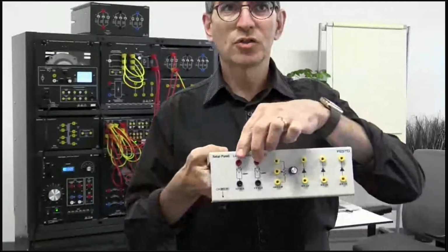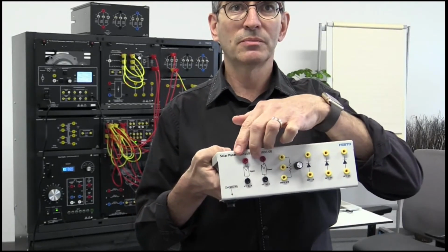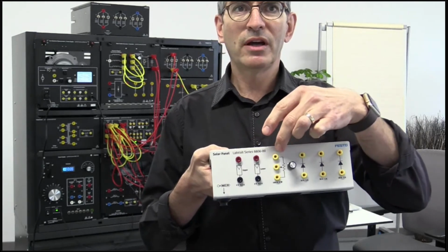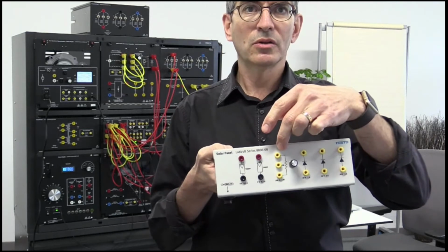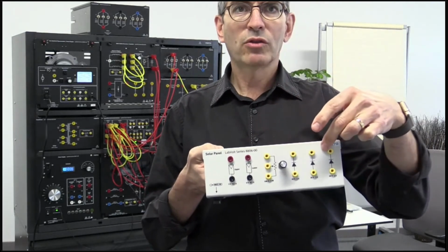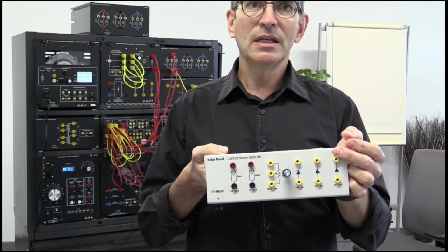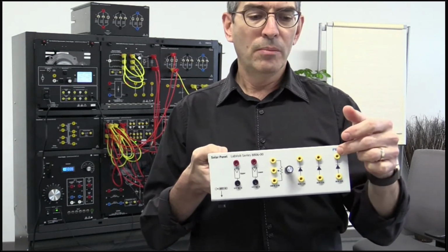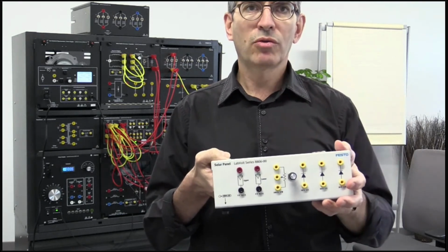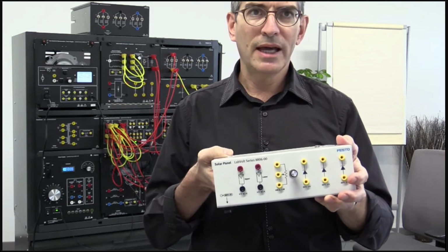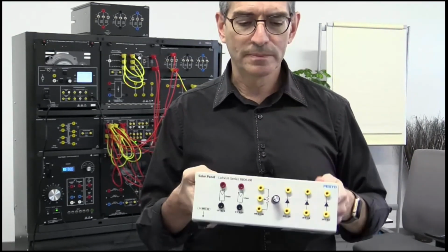So we have the connections for our two modules here, upper and lower, so it's easy to connect them in series or in parallel. We also provide the variable resistance here, the rheostat, to find the maximum power point of our solar panel. And finally, we also provide 3 diodes to be able to either bypass a module that is in the shade or block the current from the battery to discharge through the solar panel at night. So all of this is covered, of course, in the manual.